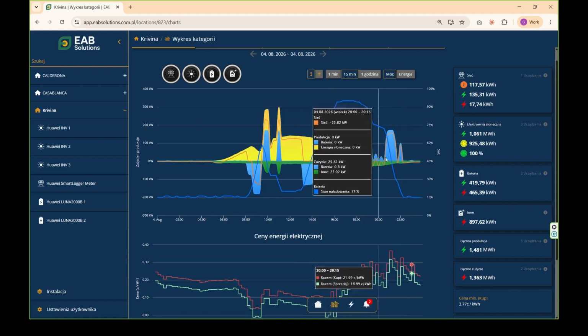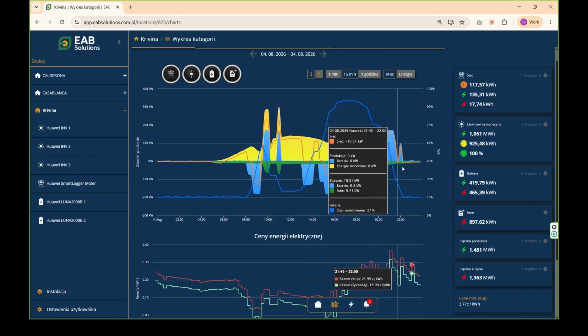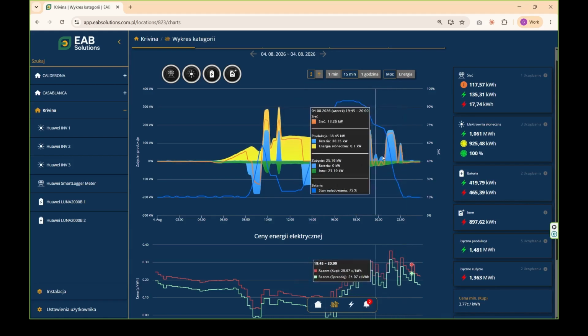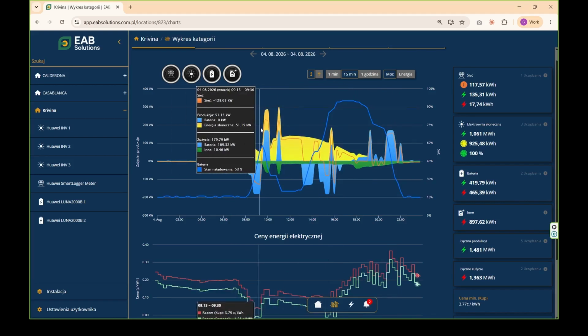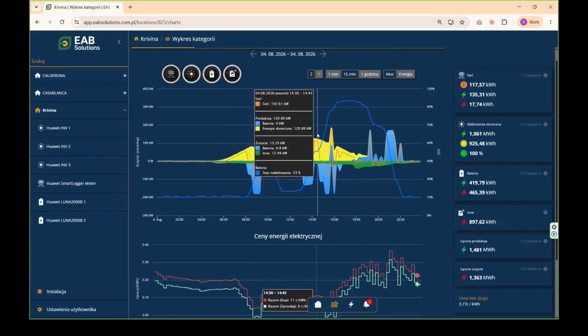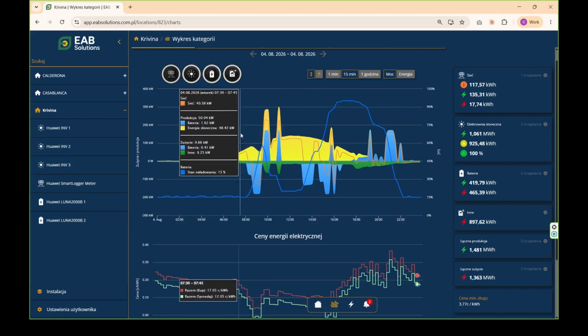That way, you reduce their consumption inside the window from 7 in the morning to 10 at night and move part of it to the night hours, making the K1 days go up and the K4 days, which are the most penalizing for the client, go down. That's a lever we use a lot on projects in Poland, and it's very interesting for our clients.